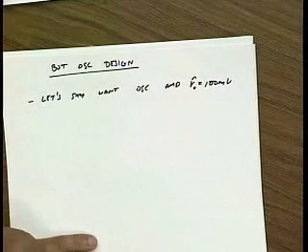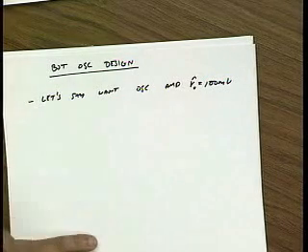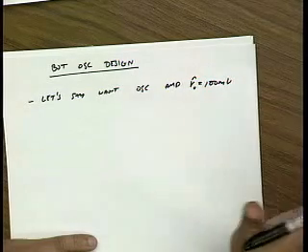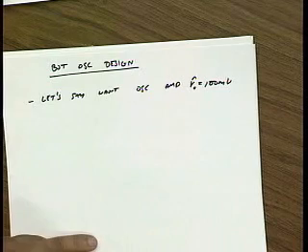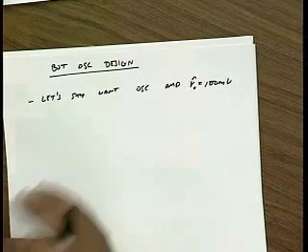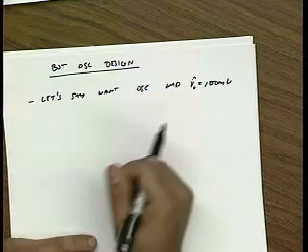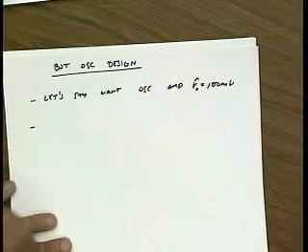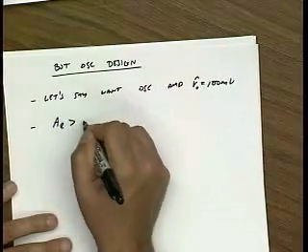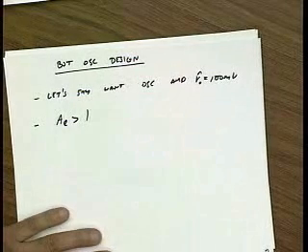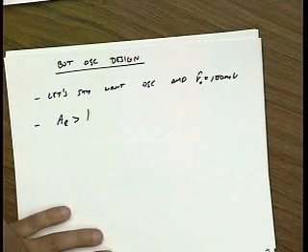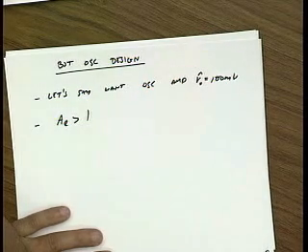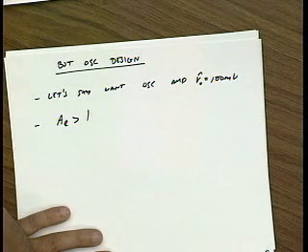You might say I have a VCO, I want a certain oscillation amplitude, I'm going to buffer it and then drive my mixers. And let's say I need 100 millivolts or a volt or 50 millivolts or whatever the case may be. Okay? So now the next thing that we choose, we know that we need a loop gain that's bigger than 1. The question is how much bigger than 1? 10, 15, 100, 1.1, 1.01, right? So this is where engineering comes in.